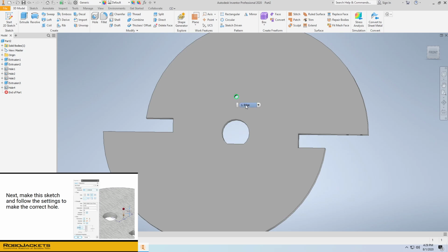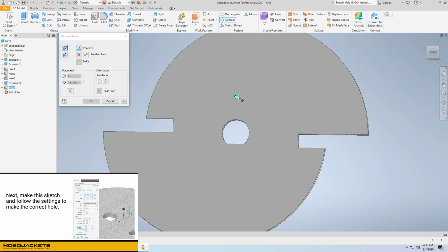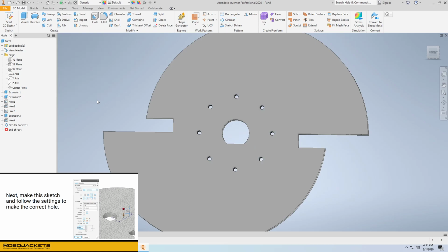That's not enough screws. So instead of manually adding each screw in a circular fashion, we'll go ahead and use that circular pattern again, choosing the hole geometry. Now you can see in this part we're using features to be patterned instead of geometries like points or lines to be patterned. Rotational axis, well, we know we made this on the XY plane. We'll mouse over these, and yep, the Z axis is what goes through. And there we go. We want 8 of these. We'll just type in 8 here. And the pattern tool automatically creates 8 holes that are circularly fashioned around the origin, with all the same specifications.